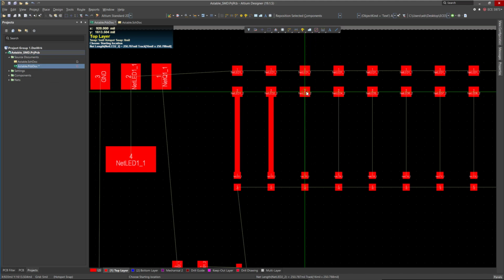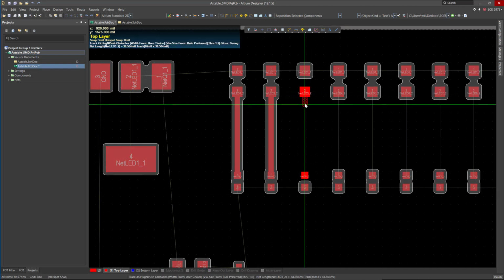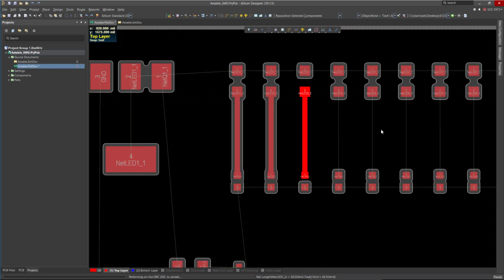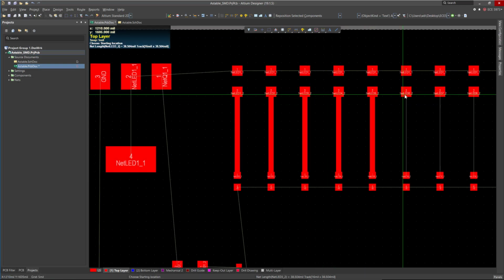Now the second thing I want to teach you today is the auto connect, or auto route, interactive routing. Basically Altium will complete the routing for you. If you start the routing now, and hold Control down and left click on the mouse, everything will be automatically routed.